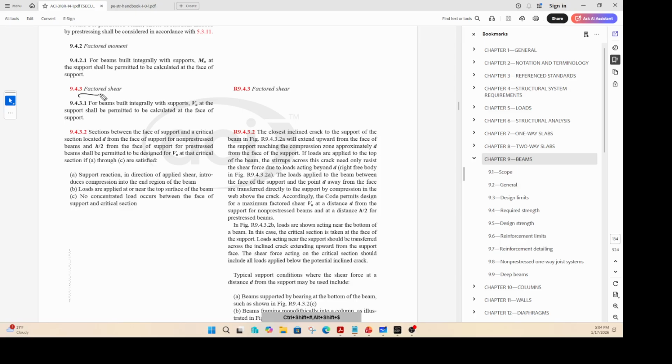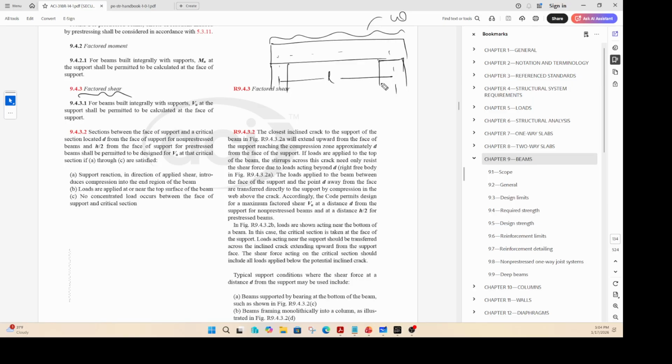So this is one interesting section wherein, when you have a beam like that, and let's say it is simply supported, and you want to design it for shear, right? Let's say here is the center line, here is the center line, and there is a UDL there, let's say W, center line to center line, L. So you try to idealize and come up with a diagram like this.